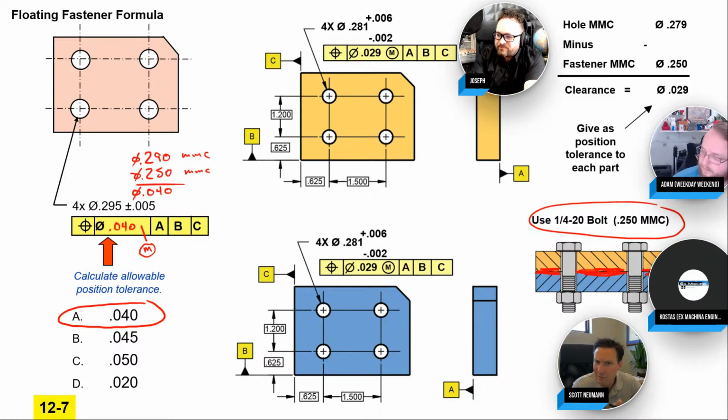But for general clearance holes, like a bolt and a screw, usually the biggest hole doesn't matter too much. They're just clearance holes. Just don't let the head of the bolt go through the hole. So there's some standard drill sizes and standard clearance holes that people recommend for bolts and stuff like that.